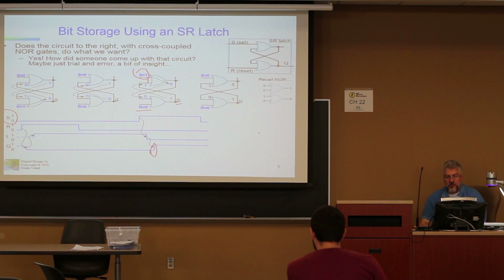And by the way, if we were to ever change S to 0, a 0 and a 1 is 0, so we'll get a 0 on the output here. We'll get the 0 over here. A 0 and a 0 is 1. And even though we change this S to a 0, our Q remains high. This remains the logical value 1, correct?